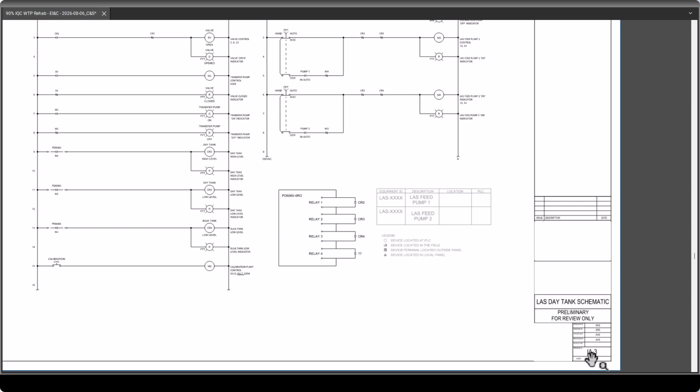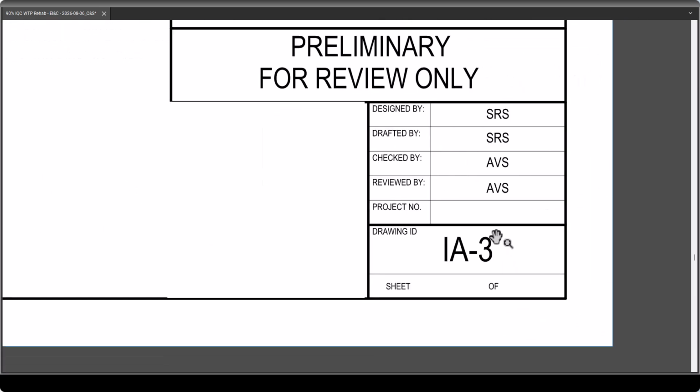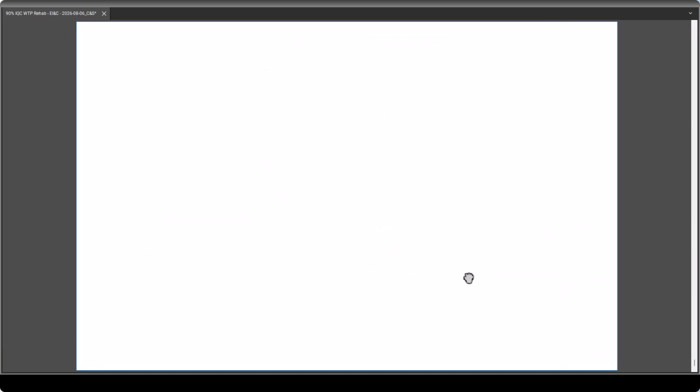So yeah, people on YouTube, I totally forgot. Make sure that your sheets are numbered correctly. And if you're doing simple drawings like E1, E2, E3, E4, make sure that you don't skip one and go from E4 to E6 or E50 to E55, because that's happened. So yes, that's something that you should always look at from the drafter's perspective.